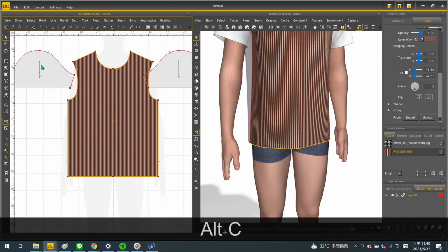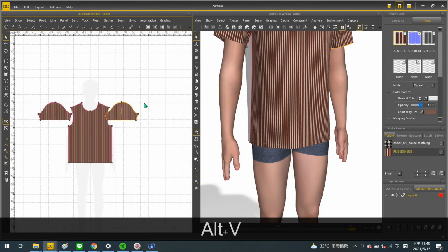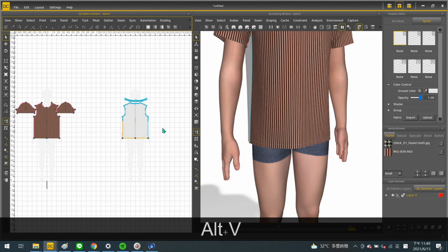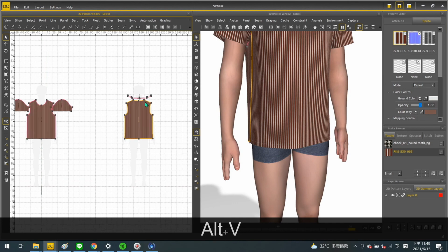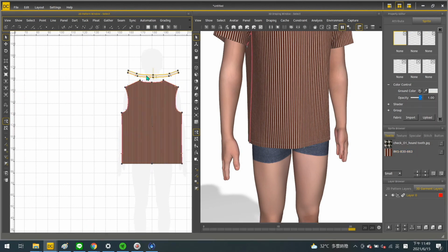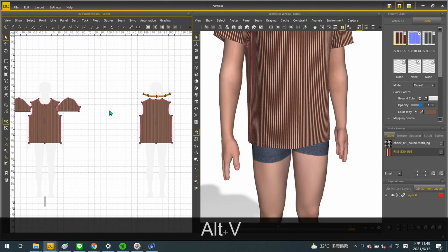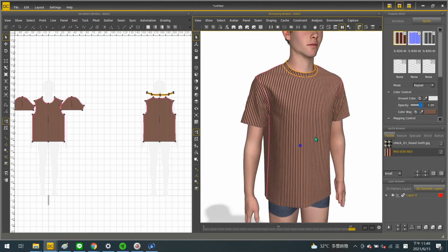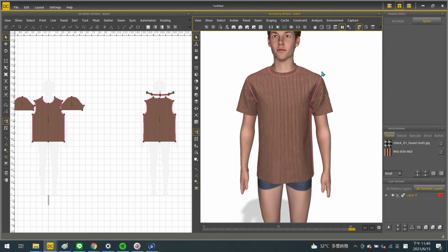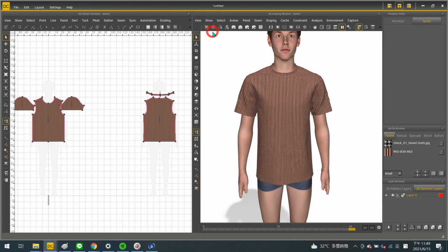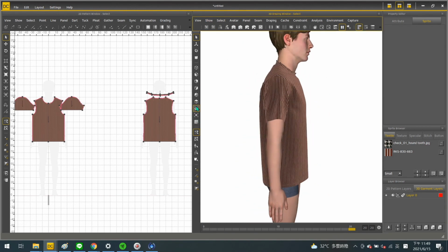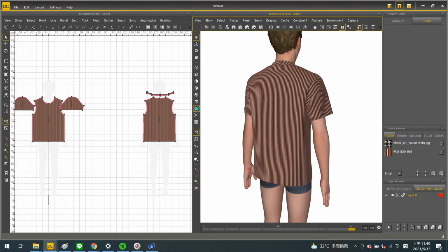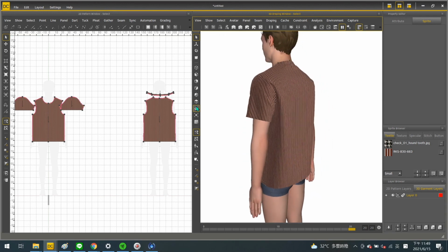Whether it is a stitch or fabric, you can use the same shortcut. And let's use the fabric on every panel to make this style complete. When your style is complete, don't forget to go into the Show menu and disable the show of lines and points to make it a clear view for your final work.